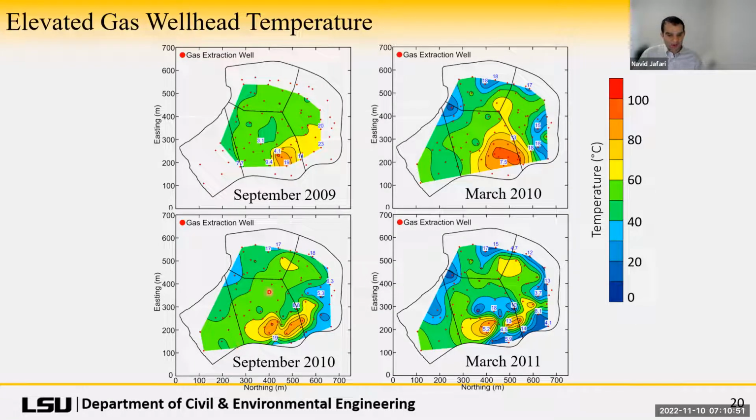And that holds true as you go from September 2010 to an even more extreme March 2011, where the oxygen concentrations are quite high. So we're probably seeing that the gas well itself, from an engineering performance perspective, potentially has seals broken and air is just getting inside the well, being short-circuited.